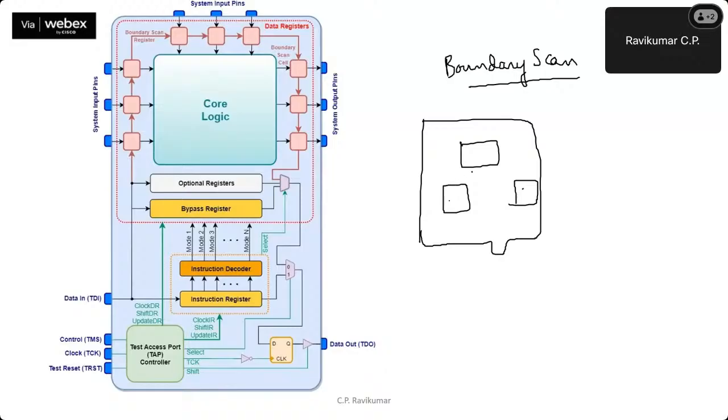Then practicing any kind of system level test must have a standard. Without this standard, it becomes very difficult to support the customers. So all the companies that were making semiconductors got together, and they came up with a standard way of testing the PCBs, and that is this boundary scan, and it is also a standard now. IEEE 1149.1 standard.